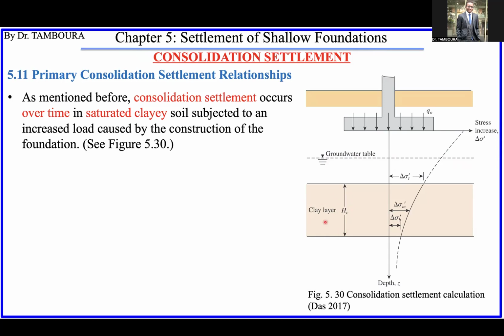So when you load this foundation, it takes time before the settlement of this clay layer can be completed because it contains water, saturated clay. So the thickness of this clay can play a significant role in the settlement.